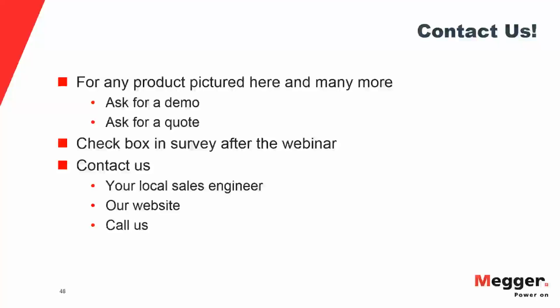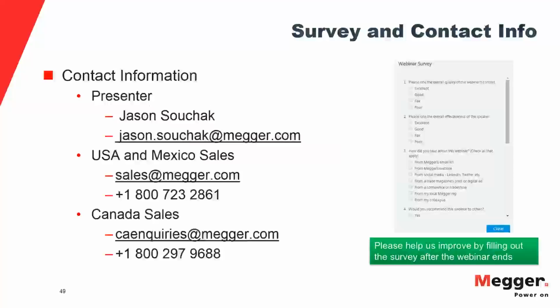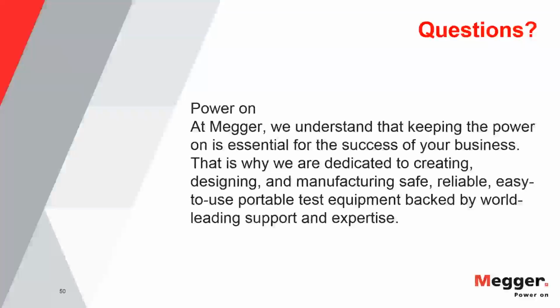Okay, hello everybody. So this is Robert speaking. What Jason presented on is mostly and specifically for offline cable testing, and that has to do with the special role that the cable has in the overall power system. The way it's used, it is the only distributed component. Most of the other components are localized and specifically located in substations. So this type of offline test is mainly an acceptance test, and is partially done as a type test in the factory.